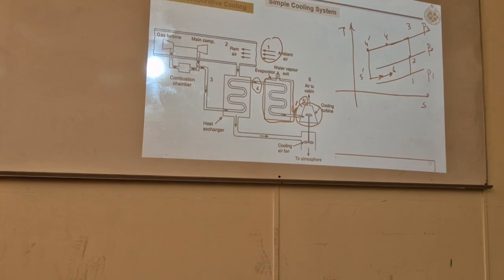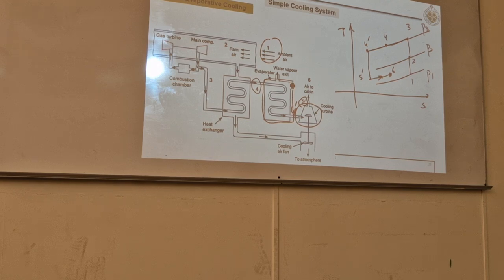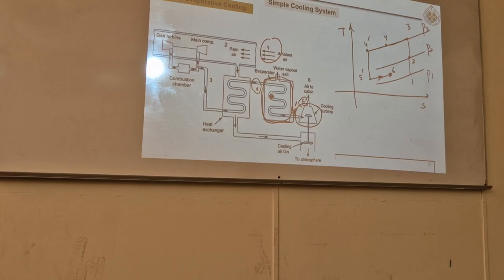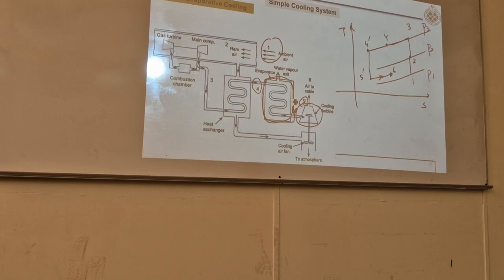Okay, for example, there is a 10-hour flight. So for these 10 hours, we can calculate how much of this fluid we should take for that flight, so that in 10 hours, all of it will be evaporated and you get that cooling. It is, for example, like taking cold water with you at some low pressure and it is evaporating.